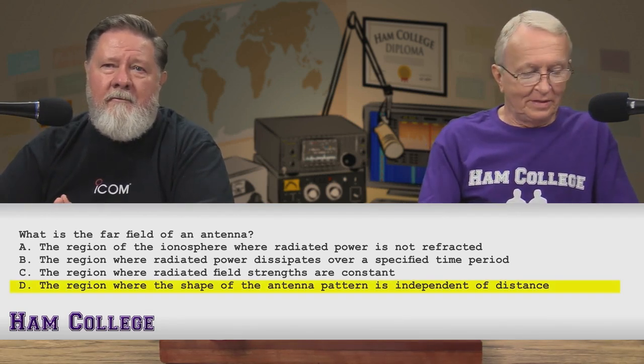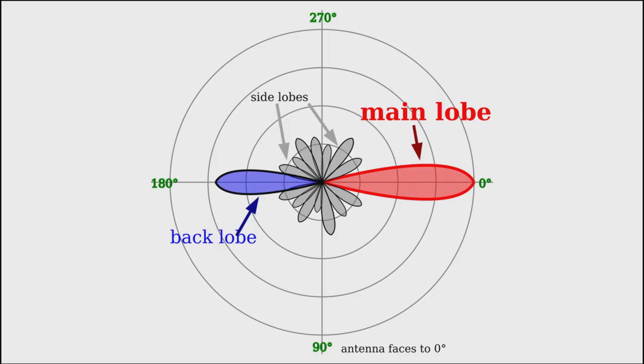I think a little explaining is in order. It wouldn't hurt. The near field refers to places nearby the antenna conductors or inside any polarizable media surrounding it, where the generation and emission of electromagnetic waves can be interfered with while the field lines remain electrically attached to the antenna. Absorption of radiation in the near field by adjacent conducting objects affects the loading of the signal generator, the transmitter. The electric and magnetic fields can exist independently of each other in the near field, and one type of field can be disproportionately larger than the other in different subregions. An easy-to-observe example of near-field effect is the change of noise level picked up by a set of rabbit ear antennas when a human body is moved in close to the ears.